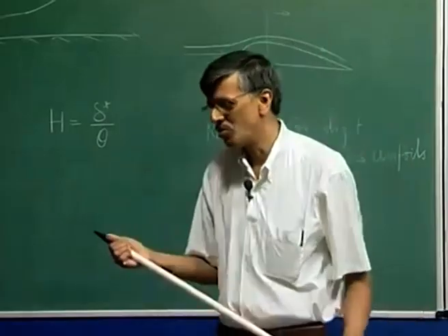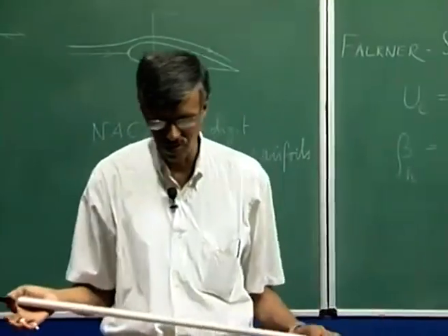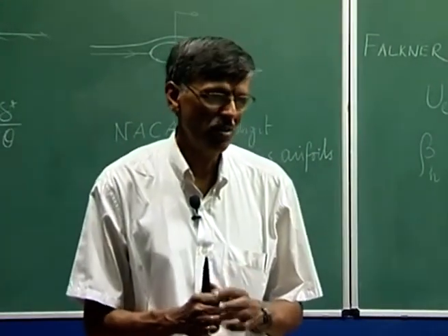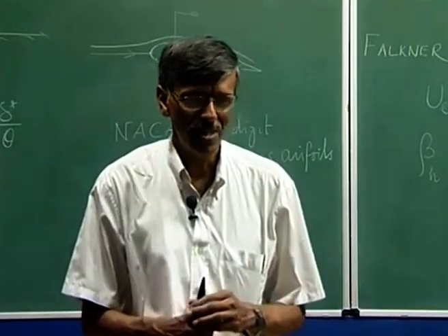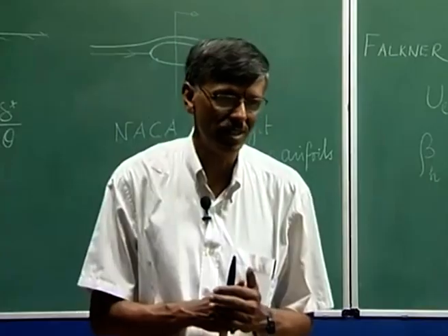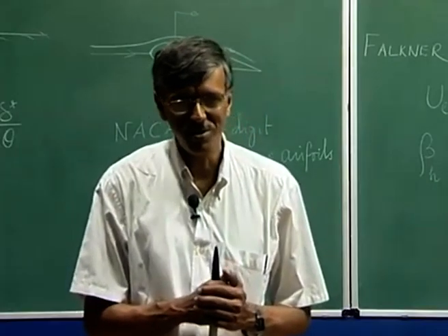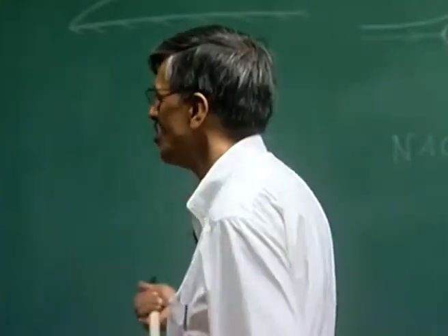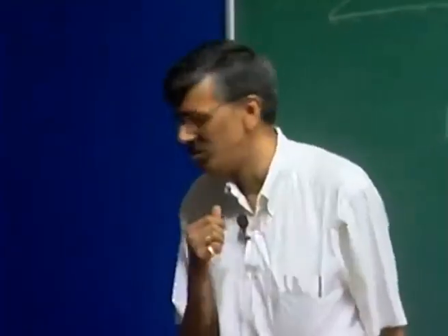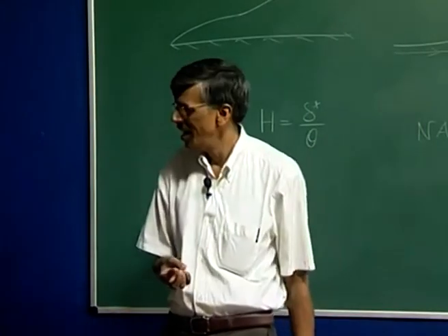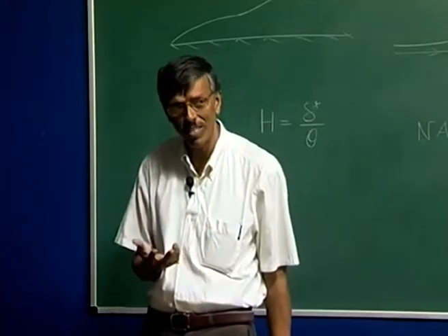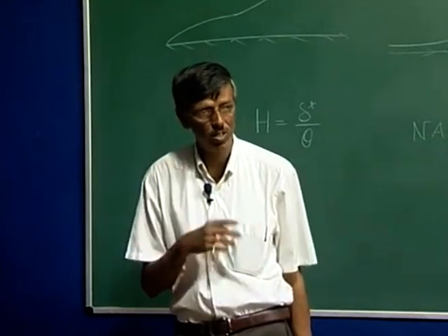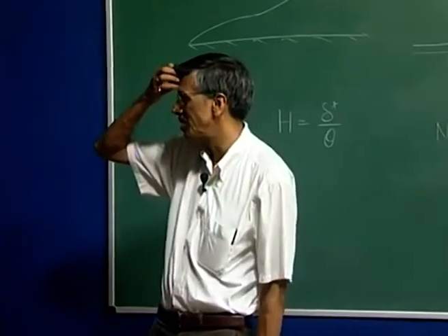Well, please do understand that Schubauer's experiment's main aim was to validate linear theory. The linear theory, what were we studying? We are studying a two-dimensional mean flow with two-dimensional disturbance field. Acoustic disturbances, can it be 2D? So, you can understand that you will have to study the flow from the perspective of three-dimensional disturbances, and we cannot use the Squire theorem, that is what we have said. For a three-dimensional flow, if you are looking at spatial instability, Squire theorem does not work. You will really have to study a three-dimensional.